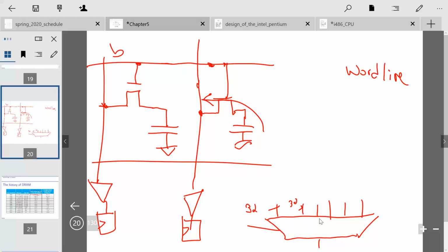So when you access the first piece of data in a row, you've now activated that row, which means the data in that row is stored in these flip-flops. Then accessing other data within that row is very fast because it's just going through this mux. As a result, you want your cache systems to take advantage of that. Our simple instruction cache does that as well. When it has a cache miss, it refills the entire cache line. We'll talk more about cache lines shortly.